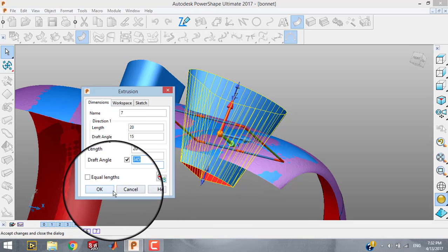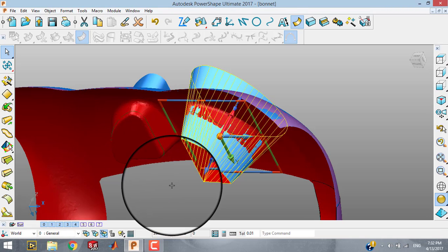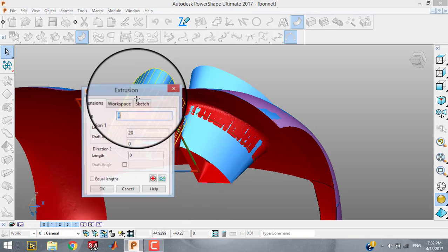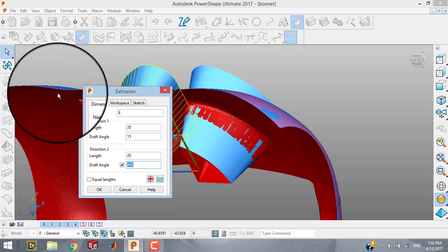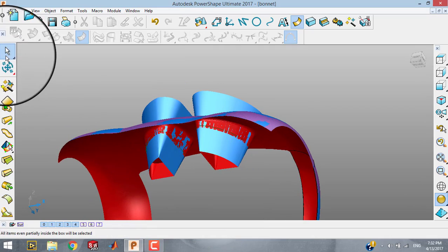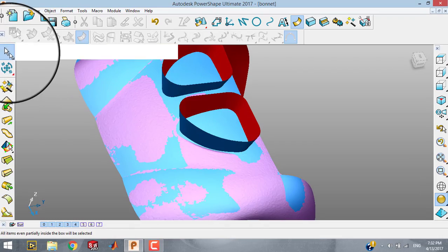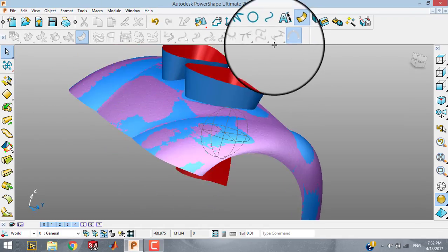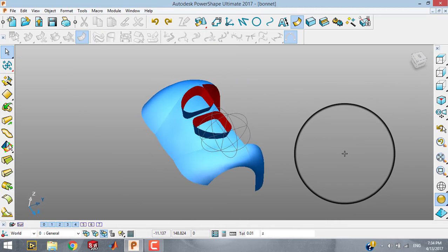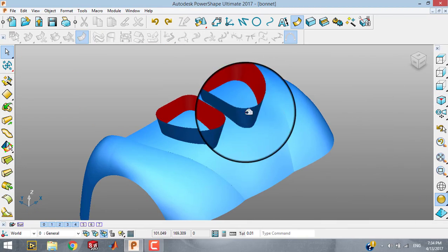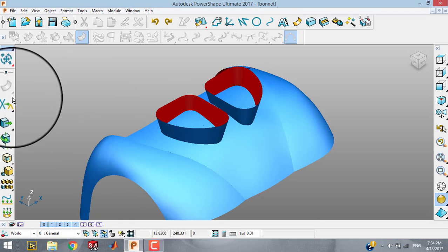Okay, we just want to make the surface pass the mesh so we can use it for cutting later. So do the same for the other side, 15 degrees and negative 15 degrees. You can make the distance any amount, just making sure that it passes the mesh. So we're gonna keep just the surface, and we're going to limit the selection. So go to edit, limit selection.